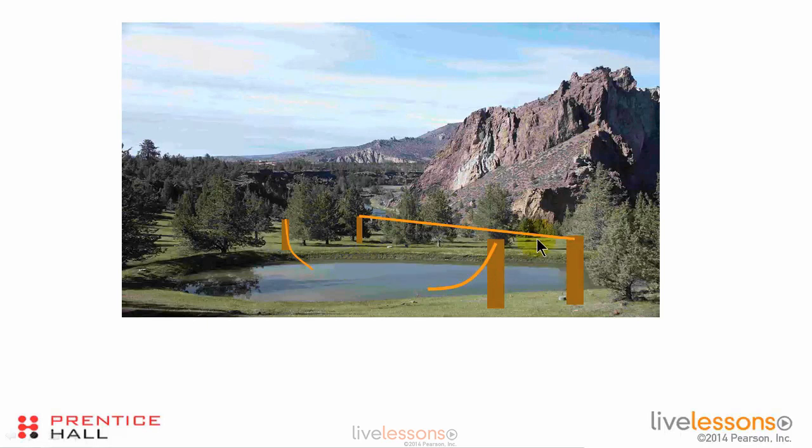The answer is the signal is going to travel much faster down this wire and get to this end much quicker in this case than it's going to in this case, because in this case the electromagnetic field around the wire has to travel through the water. So the environment is the water. The relative dielectric coefficient of water is approximately 81, depending on what kind of assumptions you want to make. The square root of 81 is 9. And so the signal is going to propagate about 9 times slower through a wire in water than it's going to in the wire in air.